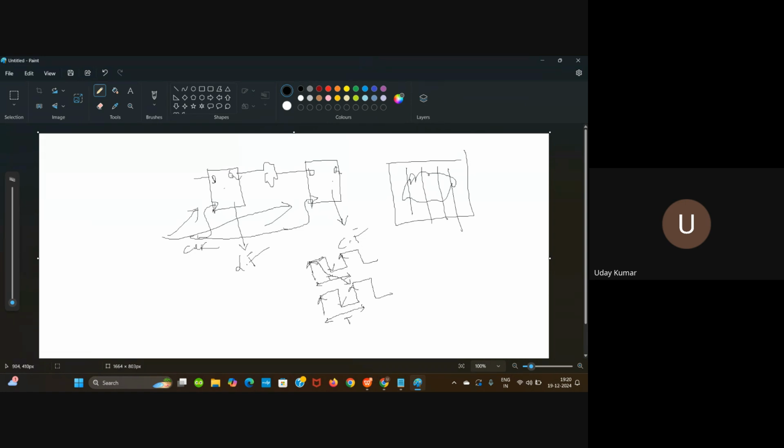So how much time it takes to travel before this gets captured at this clock edge is very, very important. That is called TPD or propagation delay of that particular combination of clock. Or we can also call it T combi. We will call it T com.